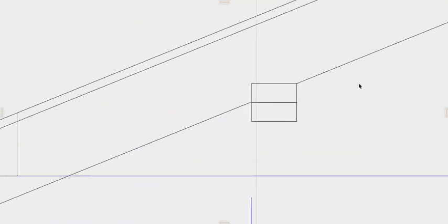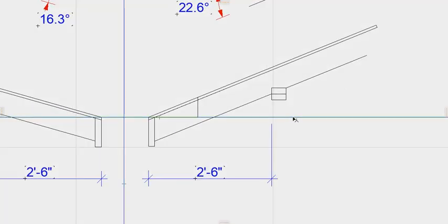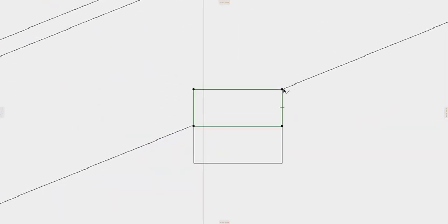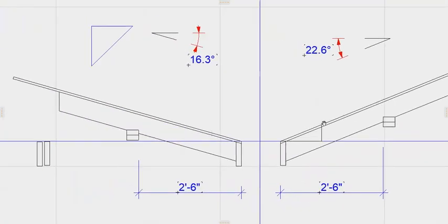Now you can grab your tape measure, your framing square, and you want to be perpendicular to that line there, or parallel to this line here, right? You're going parallel up this way. And what you want is, whatever your top plate is, if it's 3.5 like mine is, you want that little bird's mouth cut to be 3.5 inches. And so this portion here is going to be parallel to that, and the top edge is going to be parallel to this, and that's 3.5 inches from there to there. So that's the little bird's mouth there.